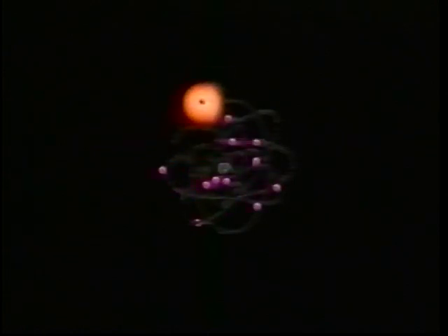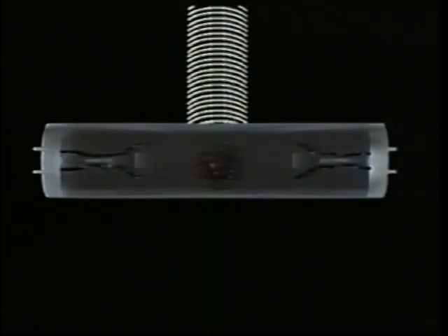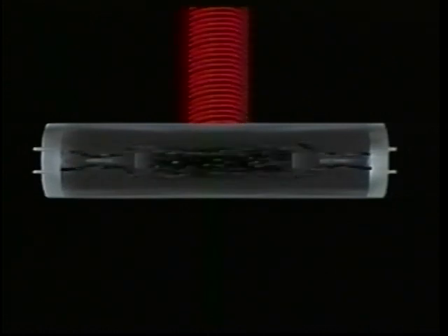The excited electrons, however, still captive, release their extra energy as ultraviolet radiation as they relax back into their orbits. This invisible short wavelength radiation strikes the phosphors in the tube coating, which absorb the energy and re-radiate it as longer wavelength visible light in a reaction known as fluorescence. The color of the light is determined by the type of phosphors used and the wavelengths at which they re-radiate the ultraviolet energy.